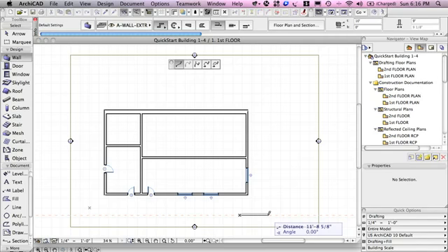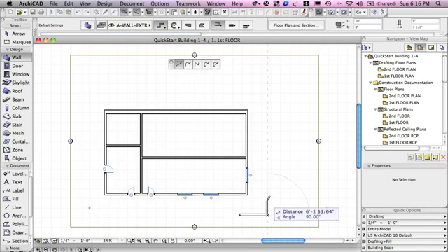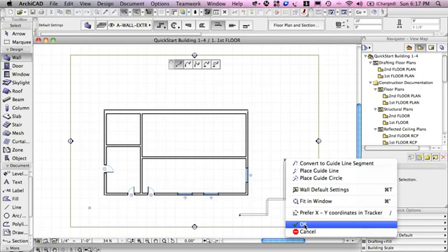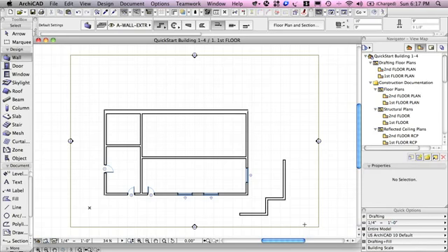My line is the bottom, the heavy line is on the bottom. And let's say that I move this up and I go across, and I'm making sure that I'm going on the guideline. You can see the angle, the 90-degree angle, and I'll go up here. And of course, normally I might want to type in values, but for now I'm simply sketching a concept. And I'll click again. Now to finish, I can either click again on that same point, or I can right-click and say OK. Those are two different ways to do it. So you can right-click often to bring up something. Cancel would get rid of all of those walls. OK will say that I'd like to finish this group.